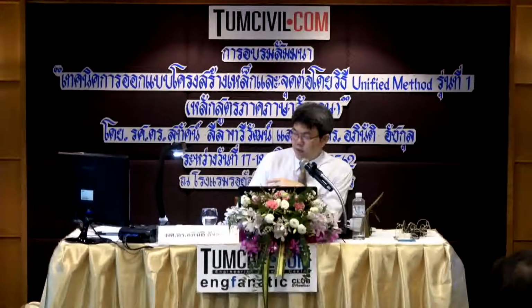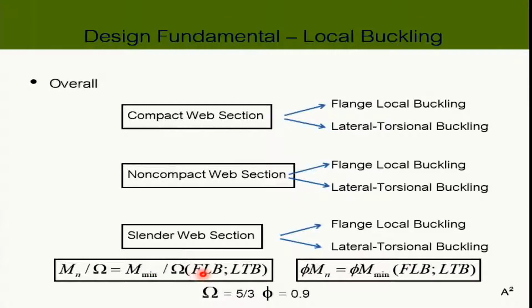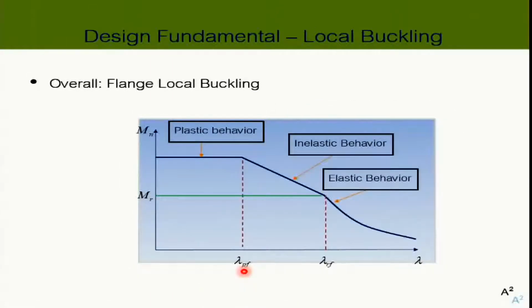And when we classify this, you just need to check whether your flange is okay, and then you check lateral torsional buckling. Two things. Very simple. So that's the flange thing. This is the general idea for the flange. So you can have